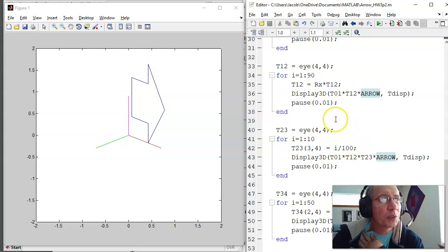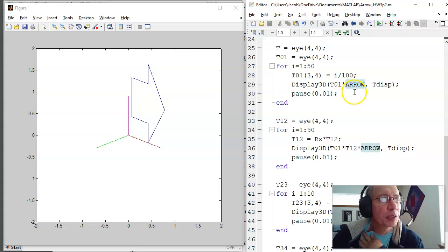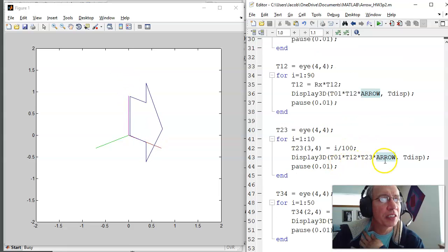And notice when you're doing this, the matrices keep on multiplying. The object is at the last reference point. Moving it back to reference frame 0, that's Earth coordinates. I can show you where it is relative to Earth coordinates. If I do a second one, it's take the object, move it back relative to the first, back to the second. Third will be your T 2,3 times 1,2 times 0,1.